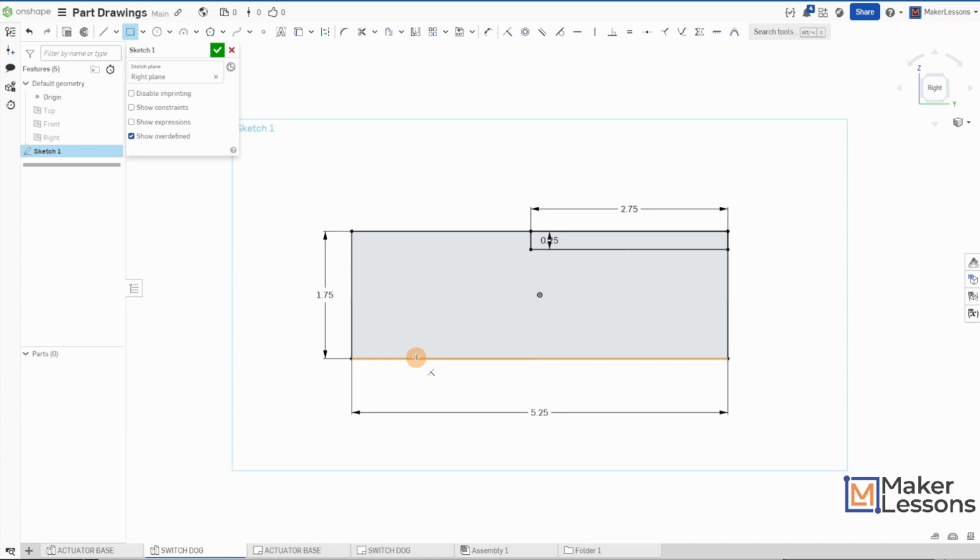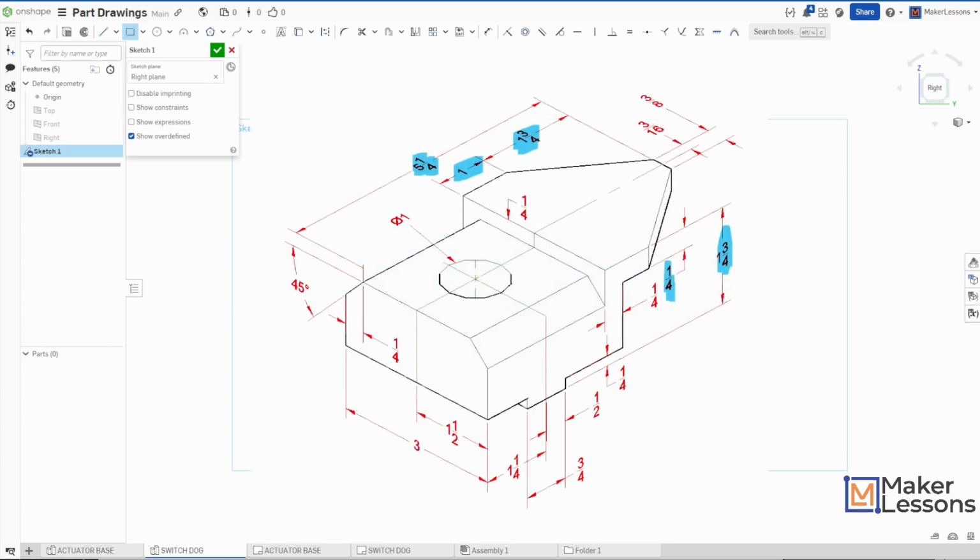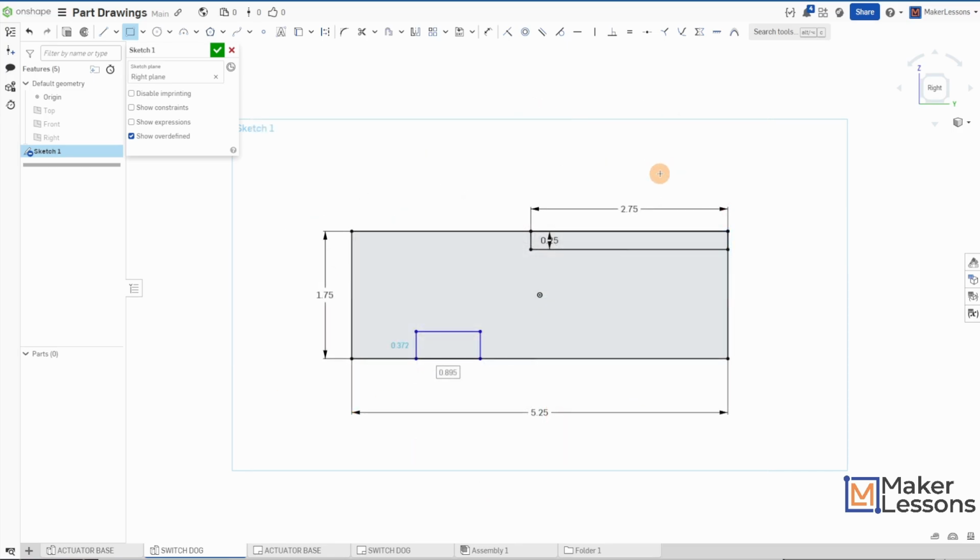For the bottom here I have a little corner point rectangle here. And let's not jump ahead and actually look at where I get the values here. So this is 3/4 wide, and width or height is 1/4 inch over there. So back over here, whoopsies, I tabbed out. Let's hit a dimension from there to there being 0.75. And then our height is 0.25. All right, but it is not placed where we need it to be.